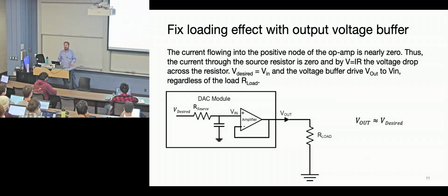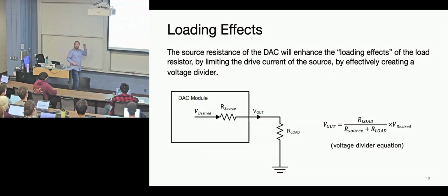Yeah. Briefly answer both of those. Sure, that's a great question. Okay. So the challenge here is when we make electronics, when we use a power supply, it provides a lot of current, right? It's great. And when we have our little symbols here, like just a voltage symbol, it provides infinite current. But in the real world, unless you pay a lot of money for that test bench instrument, it's going to have limitations in how much current it can provide.